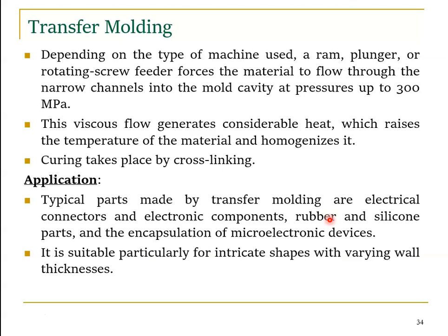Applications of typical parts made by transfer molding are electrical connectors and electronic components, rubber and silicone parts, and the encapsulation of microelectronic devices. It is suitable particularly for intricate shapes, complex shapes with very thin wall thicknesses. So up to this